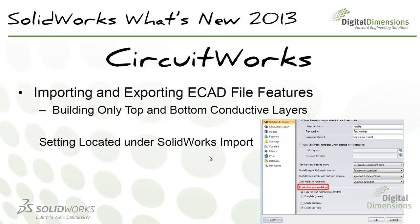Under CircuitWorks, there are some settings that you can change for how many of the layers show up. You can just show the top and the bottom layers, which will process the information faster, or you can show all the layers and get more information, but it will take a little bit more time to process. Let me show you where that setting is.